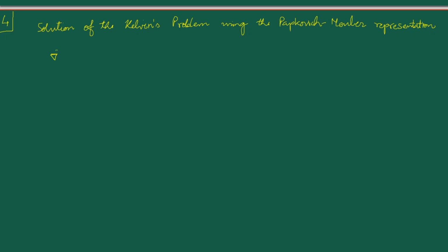One of them was del square B vector equal to rho b vector divided by 2 into 1 minus nu, and del square beta, which was a scalar, was equal to minus x vector dotted with rho b vector divided by 2 into 1 minus nu.